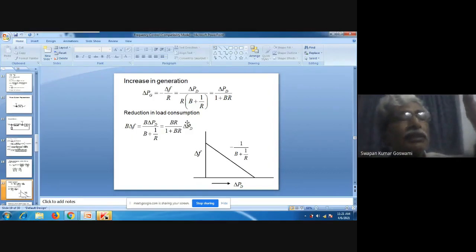But increase in generation will take some time. Reduction in frequency also will take some time. So immediately after the load is switched on, there was no time for the generator rotor to change its speed, and only then will the frequency change. So the frequency could not change by that time, and therefore the generator could not increase its power output, but the fan is getting power. Where is this fan getting power from? Is the question clear to you? What I want to know from you?